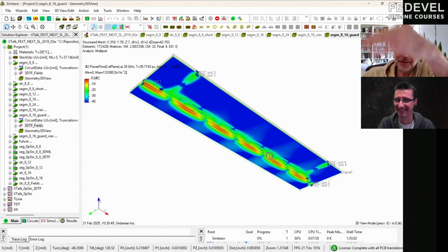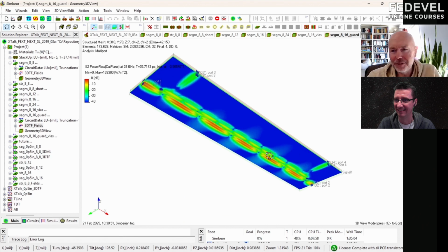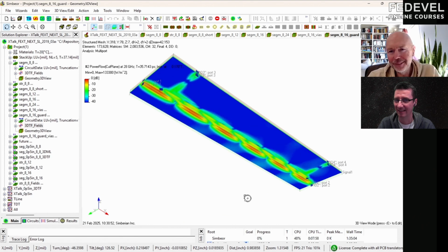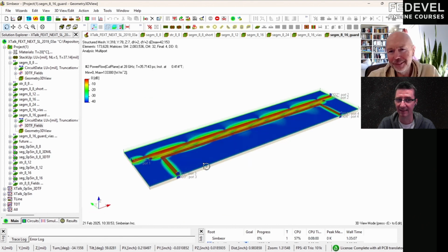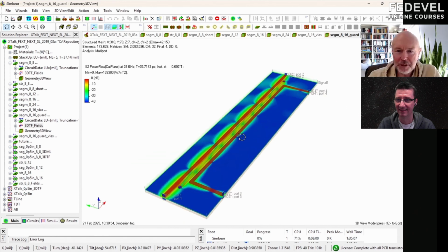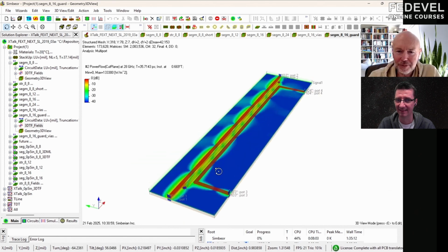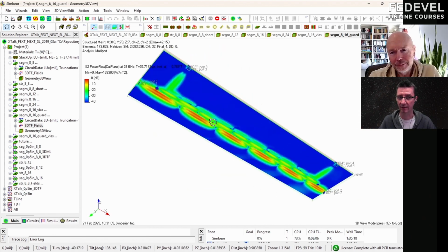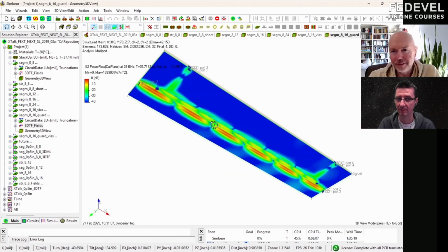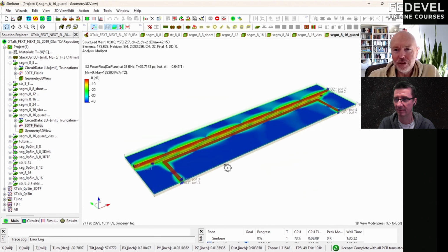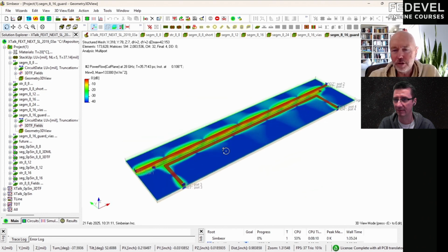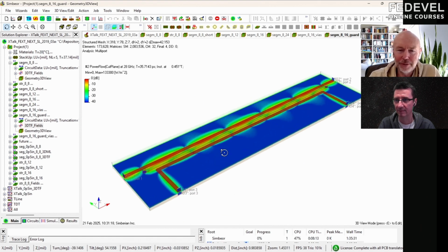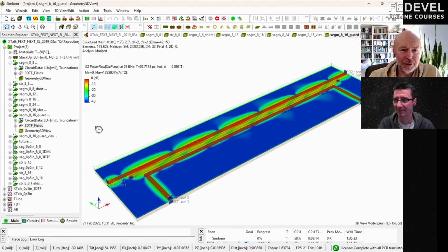They will start resonating one by one, radiate energy, but in this case, it transmits energy from here through to this victim trace. And basically, the problem is because we only have two vias, correct? Only, yes, exactly. And in this case, the distance between two vias is not sufficient. It's not sufficient at 60 gigahertz, and clearly not sufficient, or visually not sufficient, at 28 gigahertz.